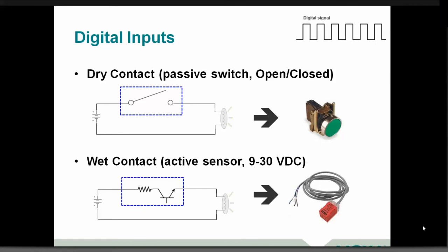We might also have different types of smart sensors here at the bottom, which might be more appropriate. So here's either a capacitive or inductive proximity sensor that's telling us if something's in close proximity, giving us that presence detection, right? We could probably spend hours just talking about the different types of sensors out here, but here are two categorical types of input devices.